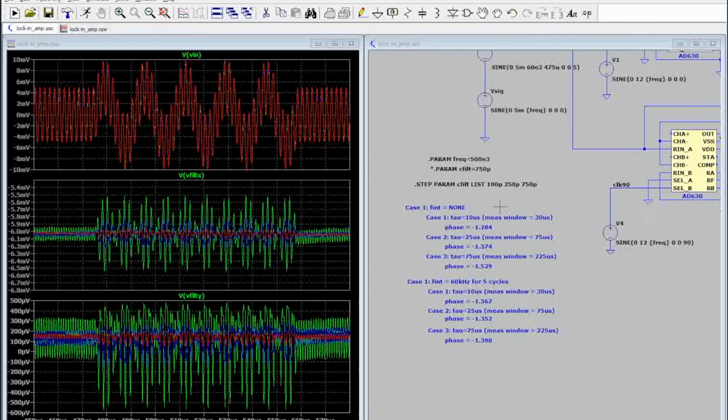So if you compare with the non-disturbed signal case, the phase didn't really move that much. It's fairly close, almost no effect on the phase error or on the phase measurement of the original signal. That is basically proven by the fact that this signal is highly randomized around the value of 6 millivolts, minus 6 millivolts, and around 0. So one would expect that there is no severe error created by the interfering noise.